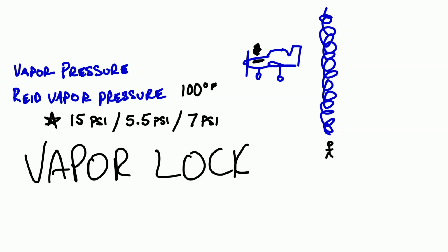On the topic of fuel meters and altitude, when we schedule fuel into an engine, it needs to take a couple things into account. We need to know how much air is moving through the engine to schedule the appropriate amount of fuel to maintain our proper mixture. And we also need to be able to compensate for the density of air flowing through that fuel metering device.